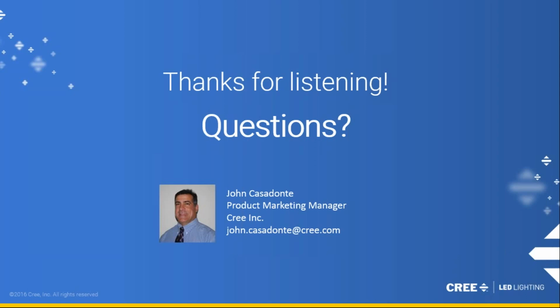Really good question. In a retail space, big box facilities, imagine all retail, you're probably going to want to consider a product, and it very well could be the exact same product look, but it might have a different CRI, and it also might have a different lumen output. So you have flexibility to look at a couple of different things. You might elect to do something a little bit different in your warehouse space, considering if it has really tall shelving and you need a lot of vertical light. That might direct you to a different type of optic on your fixture.